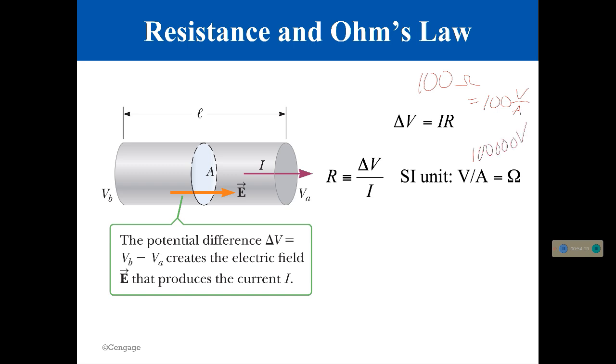So do some math for me real quick. Shouldn't take you that much. How much current should you get if you put 1.5 volts across it? Do the math real quick. You can do it in your head, do it in your calculator, I don't care, but do it. Okay, give me a number. Your skin, 100,000 ohms. You put a 1.5 volt battery across it. How much current do you get?